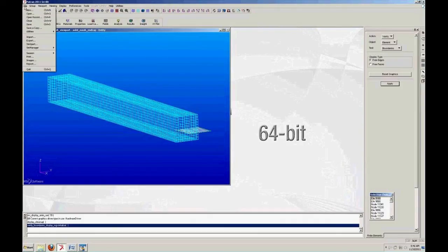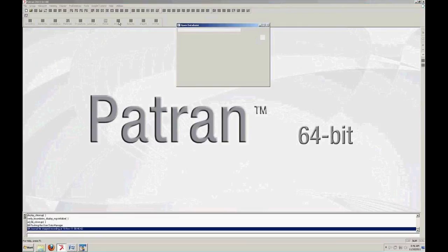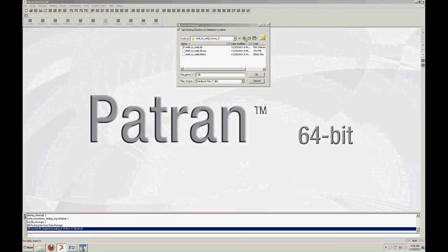Nastran is okay if your stiffness is 0, because if your stiffness is 0, the auto-SPC, the automatic constraint system I talked about, will take care of that. However, if your stiffness is very close to infinite or very close to 0, that can cause excessive pivot ratios. That's what we're going to see in the following model. Assuming my computer lets me.